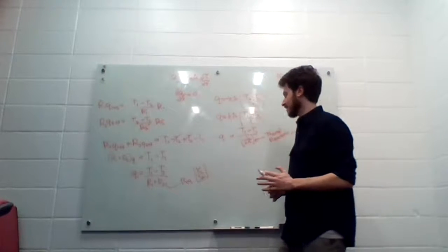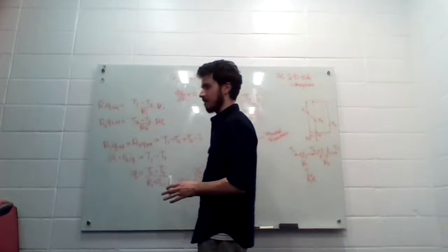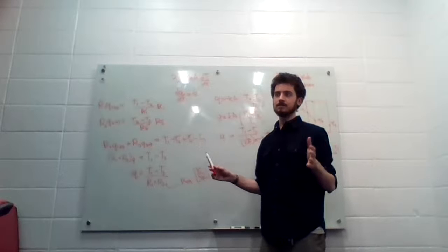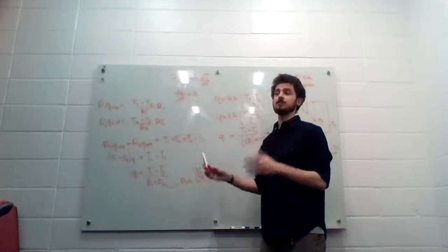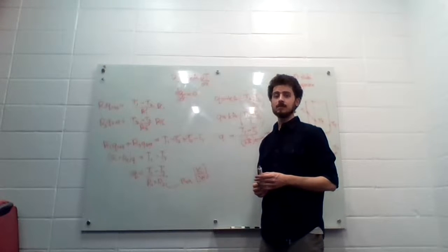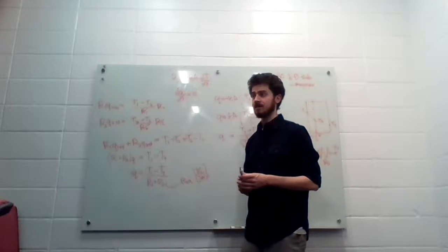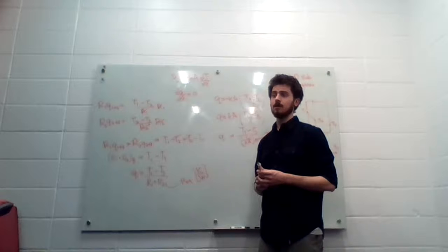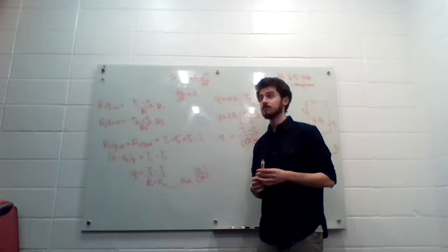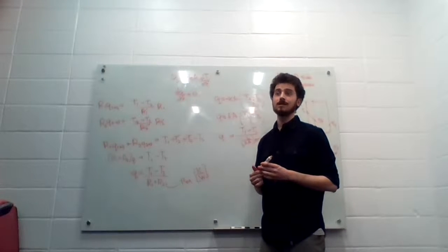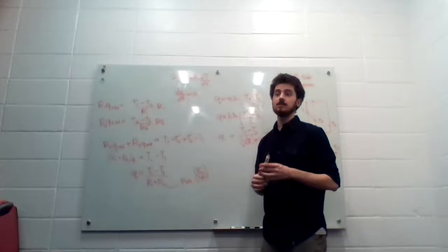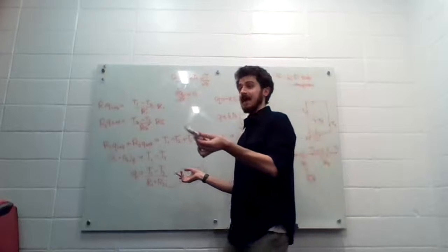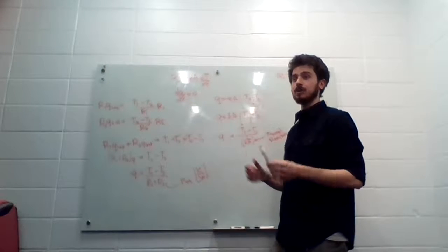Now, I mentioned this in class yesterday, and I just want to throw the caveat out on the board that when you have big temperature differences, the thermal properties do change. There'll be some appendices in your book specifically for metals, which tend to operate at a whole range of temperatures, where if you've got steel in a furnace, you will have different thermal conductivities than steel at room temperature. And actually the cool thing about that is you end up with anisotropic behavior, not isotropic.